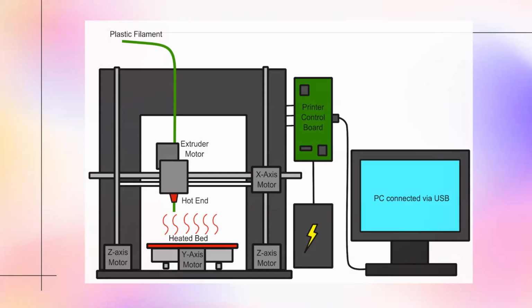And this is a simplified diagram of a 3D printer. There is a heated bed underneath. When something is printed, the bed will adhere to it, so you generally want to have a flat bottom because of that. And you also want to zero out all the XYZ axes before printing.